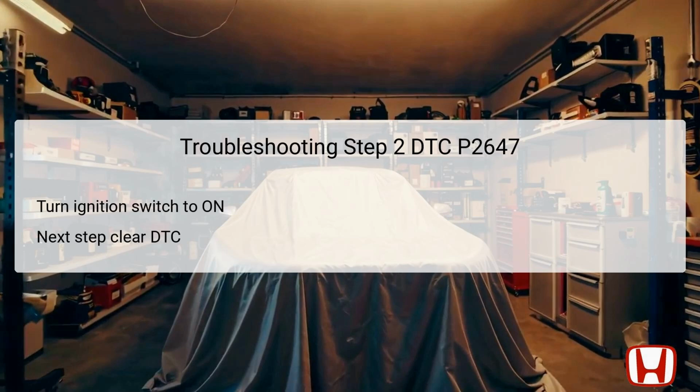It ensures that the information in the system reflects only any currently existing issues rather than historical data, which could complicate the troubleshooting process. By proceeding to the next step to clear the DTC with the Honda Diagnostic System, HDS, you can assess the system's immediate condition. This step is vital as it resets the system, enabling more accurate evaluations in the subsequent testing phase.